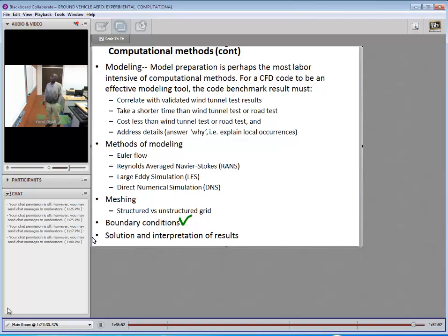Depending on the type of design that you have for cars, you have a lot of rapidly changing body surfaces. So you probably want to use large eddy simulation or Reynolds-averaged methods or some custom package that's developed in-house. For something like a bus, where there's a smooth panel for a long distance along the length of the bus, you can use the Euler method, or even the panel method, the simplified method. They give a solution very quickly, and those simpler methods would probably generate a result that's almost as good as the more complicated ones, like large eddy simulation, just because of the profile of the vehicle. The more intricate the profile, the more the need to use things like LES or some other in-house built packages.